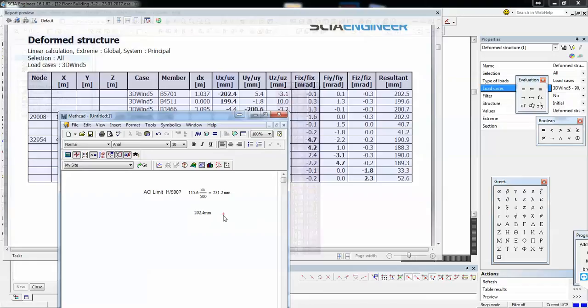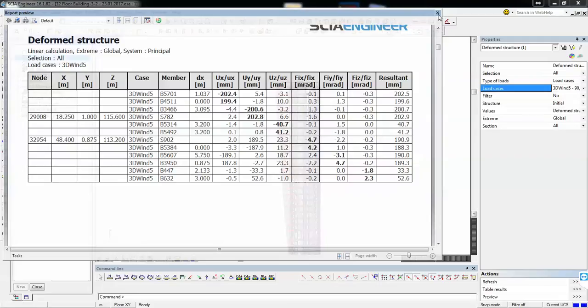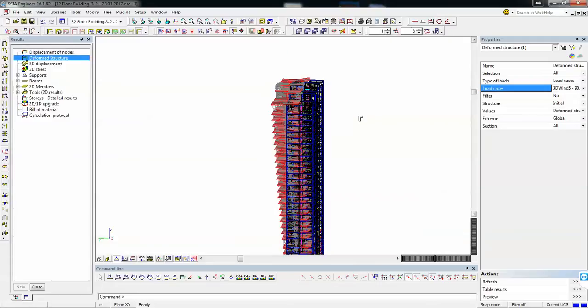So the Eurocode won't provide you this type of ratio, but rather we will assess on each level how much the relative deflection is in comparison with the capacity. So for now we did this small check, which is not 100% relevant as it's only on the pure load case.